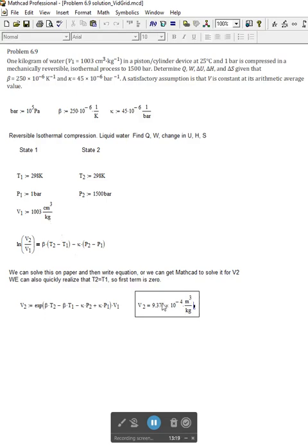And so the way to do that is when the calculation is done, you can click on the little cursor there to the right, and then I just enter what units I want. So I want to go from meters cubed per kilogram to centimeters cubed per kilogram. So I just type centimeters, caret, cubed, and I select all that, divided by kilogram. And so now I have my units consistent with what I had defined them to be earlier.